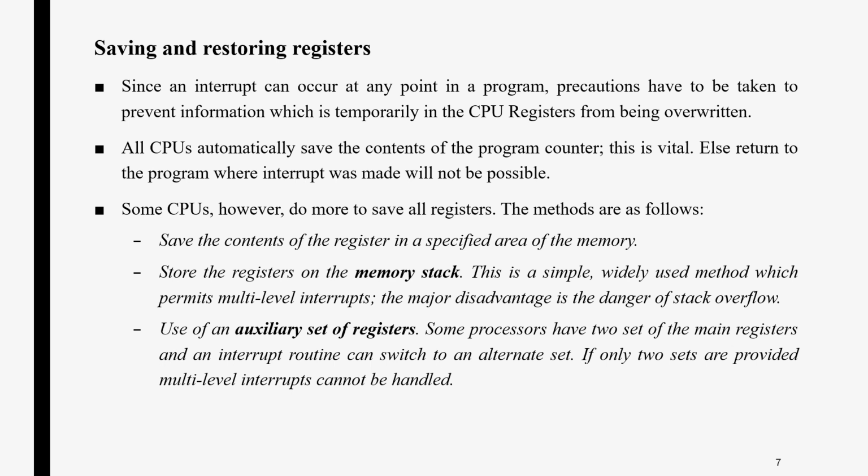One is to save the content of the registers in a specified area of memory. Second is to store the registers on the memory stack. This is simple and widely used, and permits multi-level interrupts, and the major disadvantage is the danger of stack overflow.